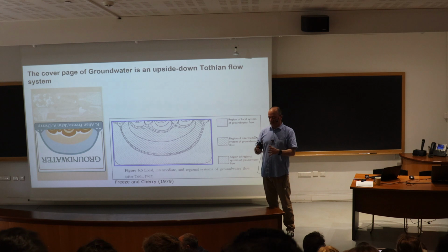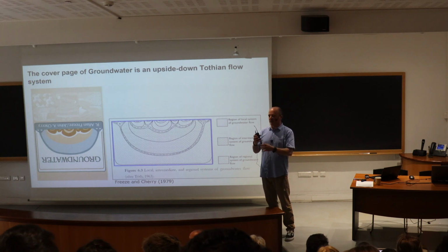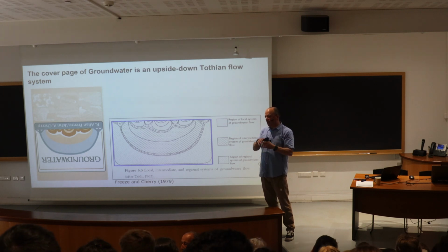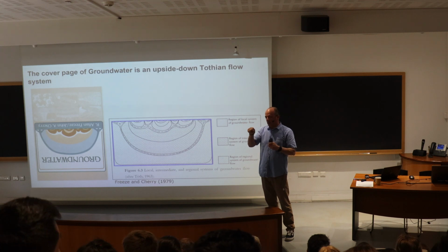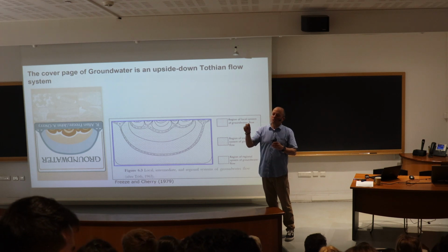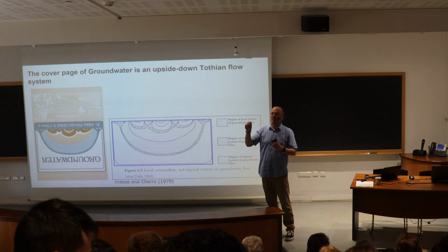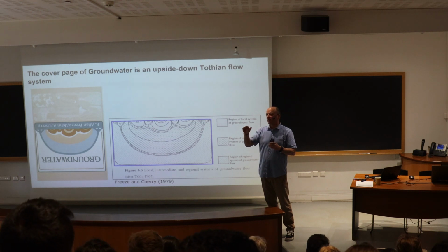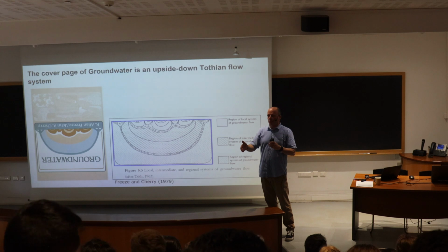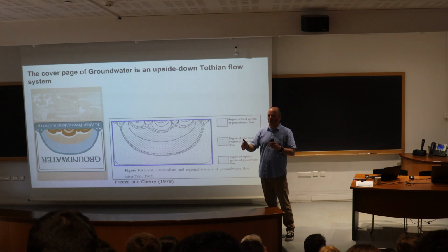But then you could take the same material, put it into a column, and run a tracer experiment. And then if it's controlled, you get your breakthrough. From the breakthrough curve, you can get the arrival time of the center of mass of your tracer, which is actually an indication of the velocity. And you might find out that, well, if I use the lab porosity that I got, it doesn't fit.